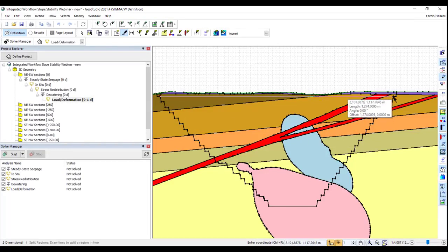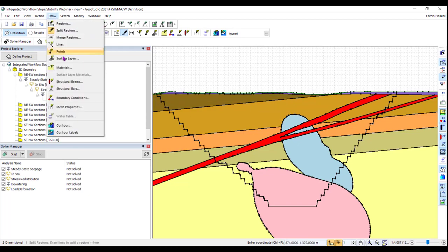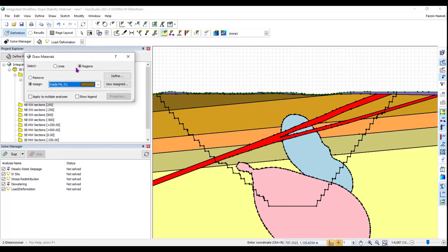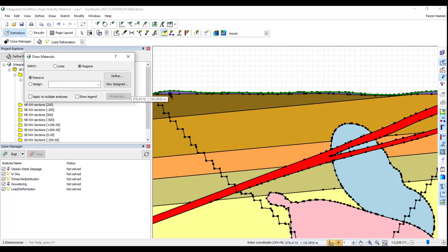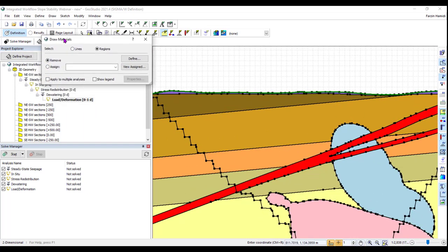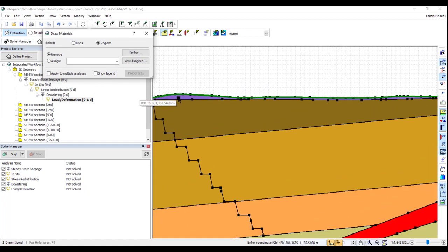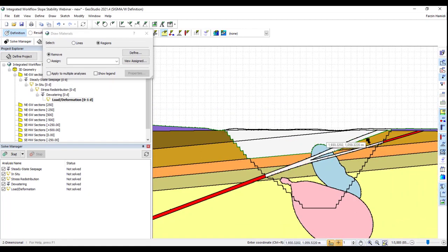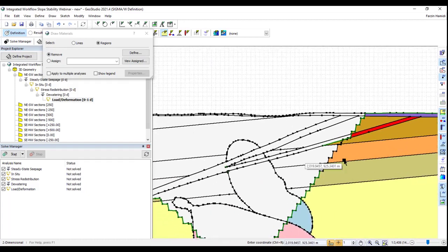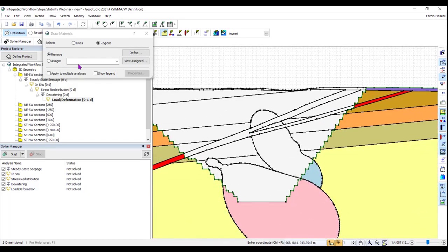We are able to model the complex excavation stage by cutting the domain. Also in Leapfrog, we can include those excavation stages and import them into GeoStudio. Or we can make it simple and change the cross-section stage and include just a single pit wall. But we make it simple in this example. We remove all the material which is inside the pit, and we have to make sure to remove it from all the corners.